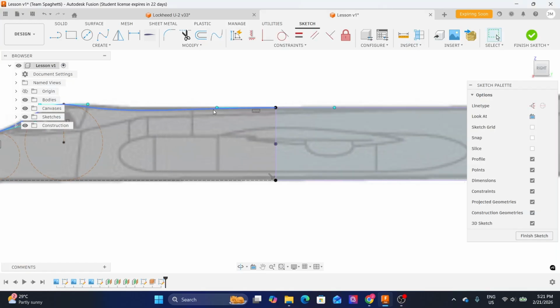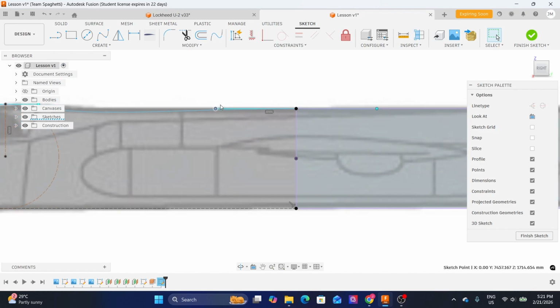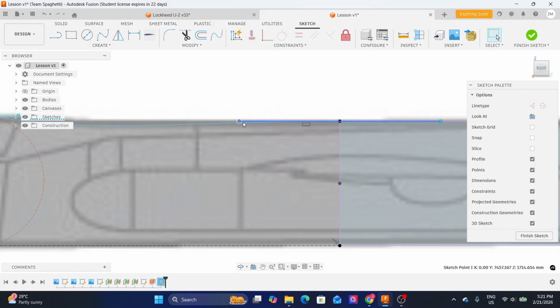How about let's try here. You see, that's the challenge of using the fit point spline and the tangent handles. So you really have to be patient, and it's really trial and error just to get approximately close to the shape that you're trying to create. So let me try at this portion.